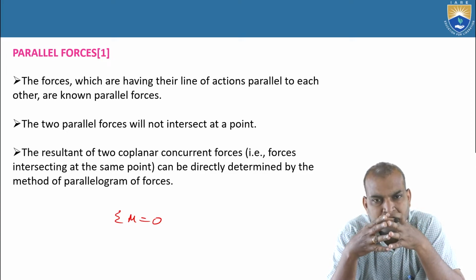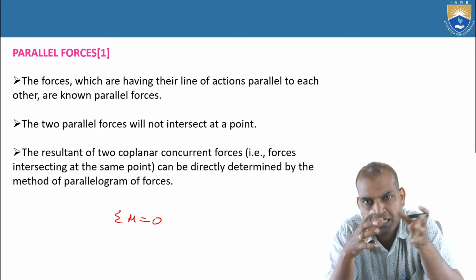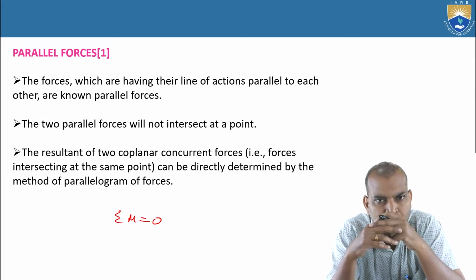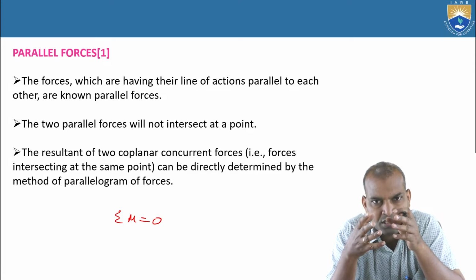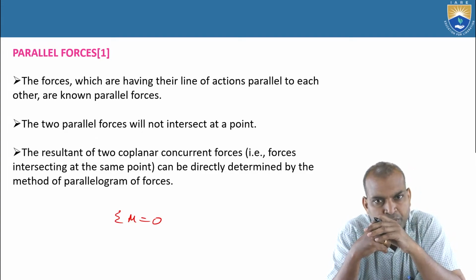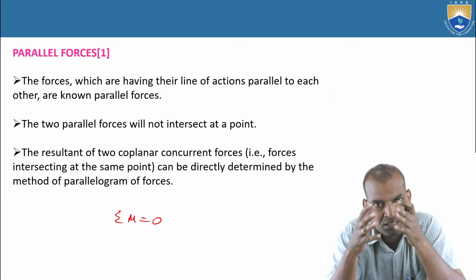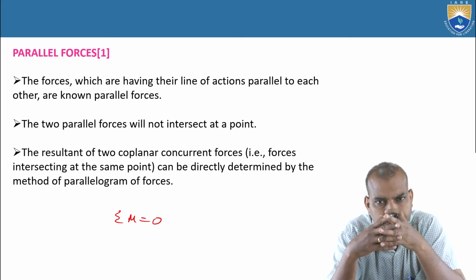In resolution, when forces act with some inclination, either an acute angle or an obtuse angle with respect to the reference axis, those force components can be resolved into rectangular components, such as horizontal and vertical components, again using trigonometry. That means horizontal components using cosine theta and vertical components using sine theta, with reference to the same axis for all the forces.